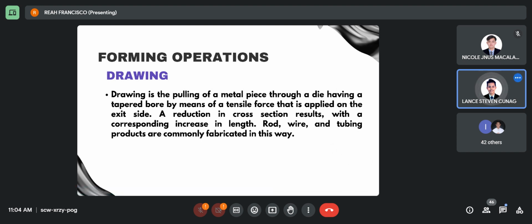So it is a metal forming process in which a metal rod, wire, or tube is pulled through a die to reduce its diameter or lengthen it. This process is vital for industries that require precise control over the dimensions of their products, such as electrical wires, cables, and precision components. Drawing not only reduces the diameter, but also enhances the mechanical properties of the material, making it stronger and more ductile. The process can be performed on a variety of materials, including metals and polymers.